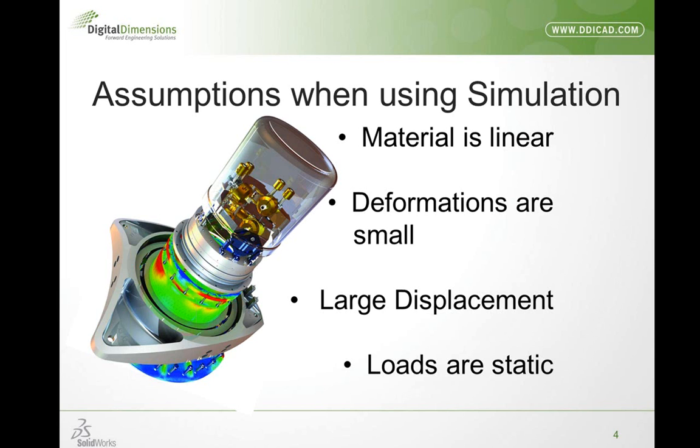If I take this paperclip and bend it a little bit and then let go, it'll go back to its original shape. That deformation we experience is our elastic deformation, and that is what we can simulate with these two packages, the Designer package, the static analysis, and the Professional package. Now take that paperclip and add some more force to it so that it plastically deforms as well as elastically deforms.